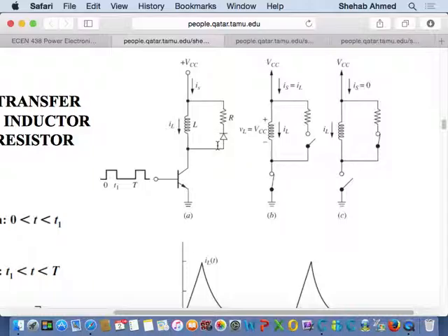If you're pushing forward current to the diode, it will turn on. So the current will flow through this freewheeling circuit here, right? It will never be going back to the supply, because for it to go back to the supply, it has to go back through its negative terminal as well, right? There has to be a closed loop, right? So there is no closed loop between the supply and ground here at all, because this is an open circuit. So it will just flow through here, and the energy in the inductor will be dissipated in the resistor.